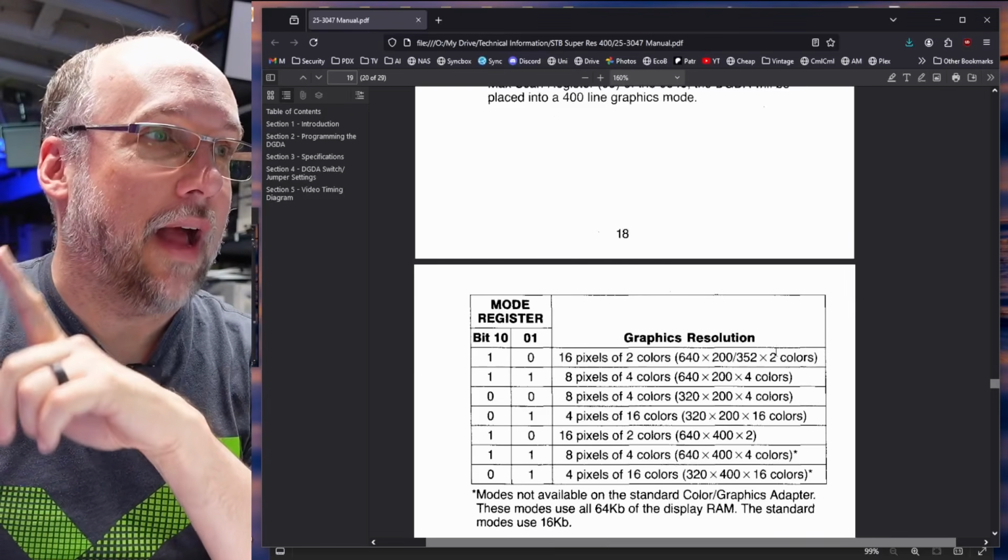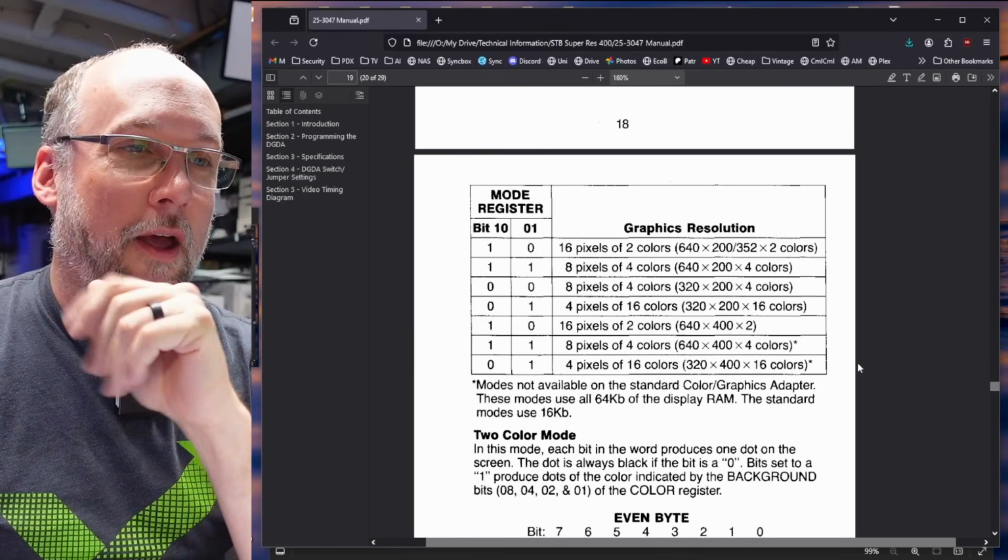The problem we're having with this card is somewhere between the RAM itself and whatever is generating the video display. If you think about the 640 by 200 mode, that is literally just outputting a serial stream of data from the RAM to the display. And the fault is exhibited there among the other modes as well, where the bit planes are showing it. But that is really an obvious place with that black and white 640 by 200 mode, where we just have missing pixels. Now the manual for the card actually has some really useful information that can help us with this.